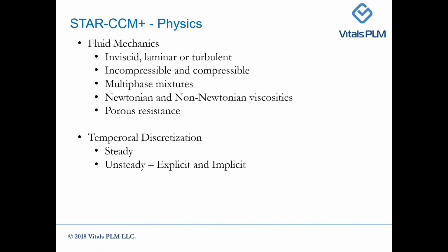For physics, we can solve inviscid flows, laminar and turbulent. We can solve incompressible, compressible, multi-phase mixtures, Newtonian and non-Newtonian, porous resistance, steady and unsteady, both explicit and implicit.